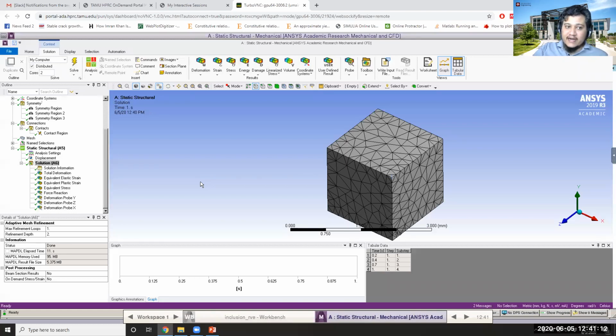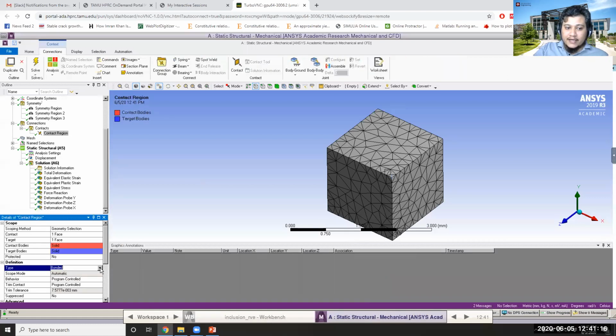Okay, but if it is not going away and coming together very fast, you can run it in quasi-static, and the contact condition for that is going to be either of these three things. It can either be frictionless or rough or frictional. All these three options will allow separation between the two bodies. I hope I have answered your question, Brendan.